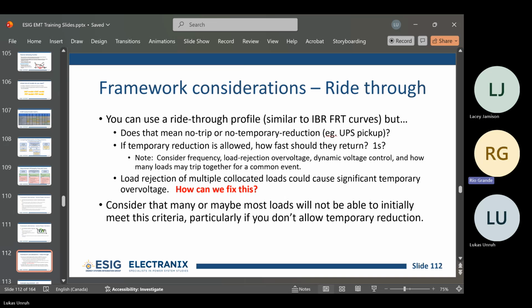The problem is for frequency ride-through, it's a little bit easier because you can link frequency ride-through to under-frequency load shedding and loss of load expectations and all that type of thing. For voltage, it's much more complex to figure out what maximum is. And it's going to change, right? The system operators know how often their grid fluctuates, or the maximum and minimum voltages they'll see on the system, and they can do probabilities and figure that out too.